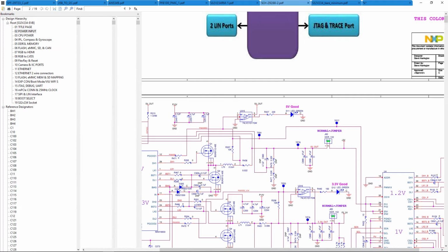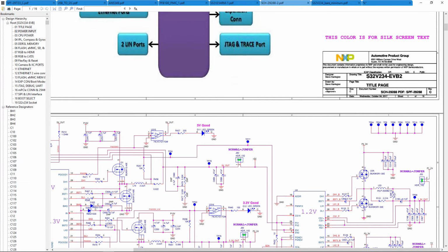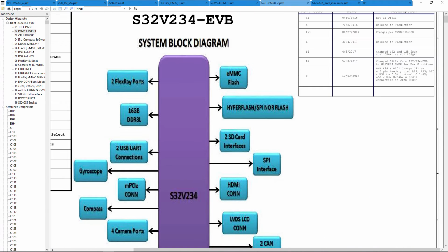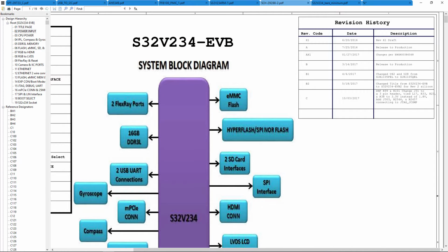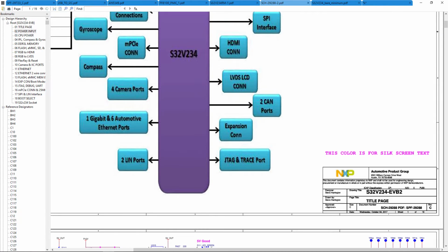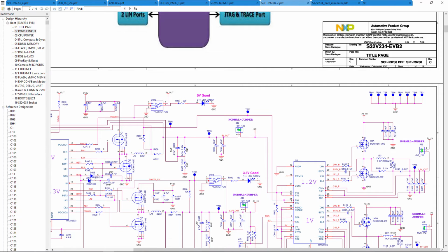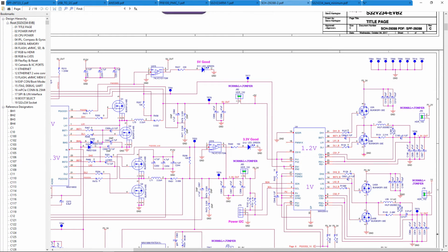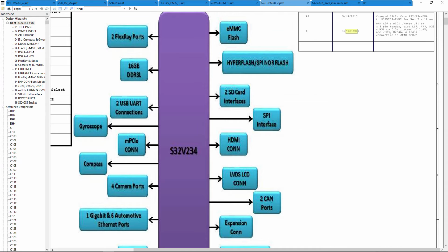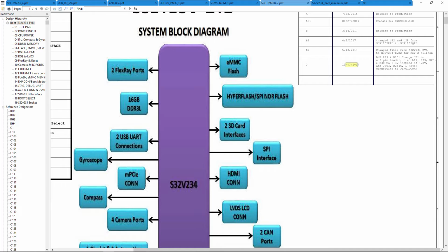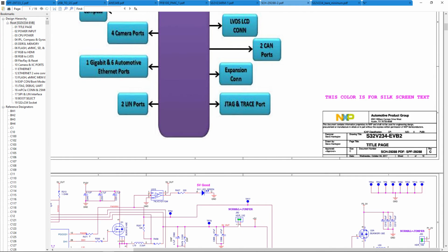All right, so let's go about and see what we're really designing. Now, the circuitry looks a little complicated, but in reality, when we're designing a board like this, mind you, this board has been designed in 2016, 2017, and in the span of 4 or 5 years, there are better components that we can select. So we're also going to look at how we're going to make this board based on today's components, because here what they have is the power delivery for any of these highly computational processors is quite complex, because powering this processor requires different voltages for different parts of the processor to function properly,